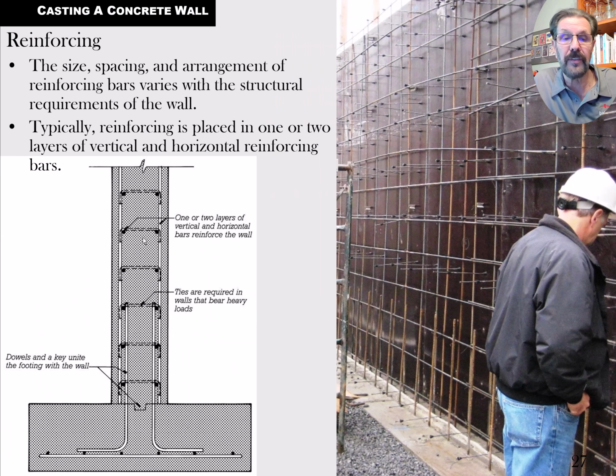So let's see if I can see some pictures here. This drawing on the left is showing you a little dowel sticking out of rebar. They're usually made of actual reinforcement bar with bumps and a hook bit on them, that are tied to the mat of steel down below in the pad or the continuous footing.